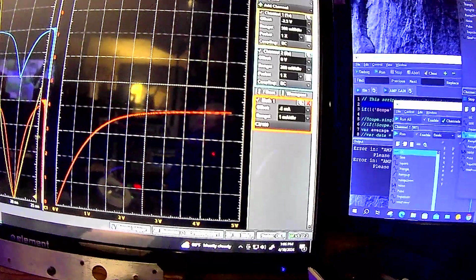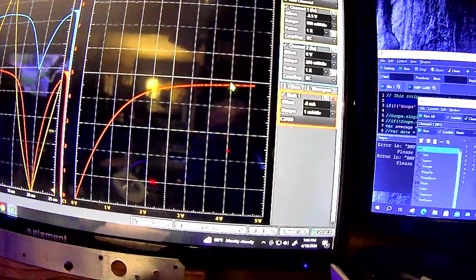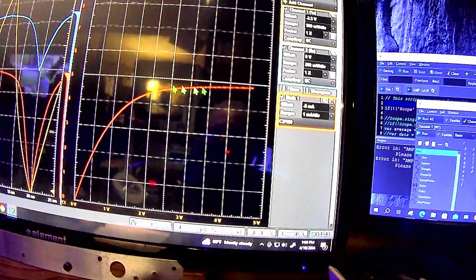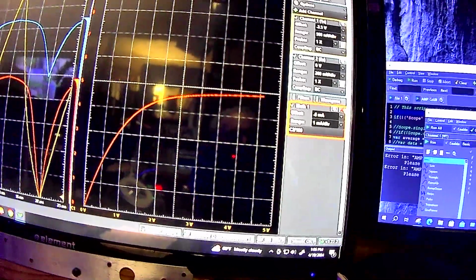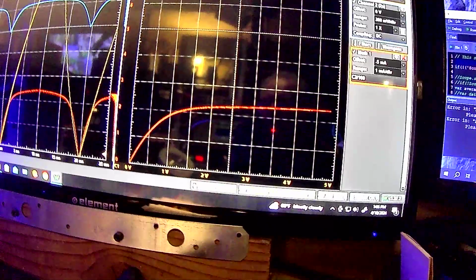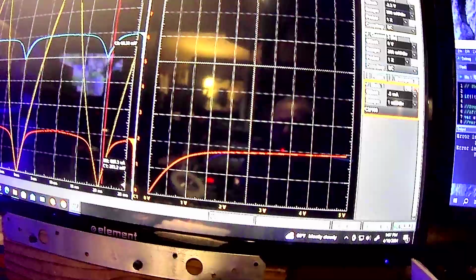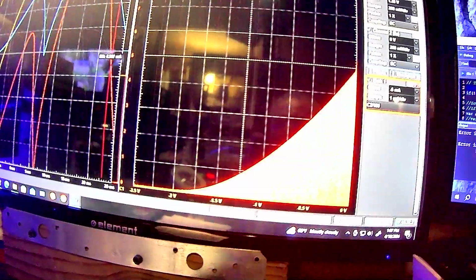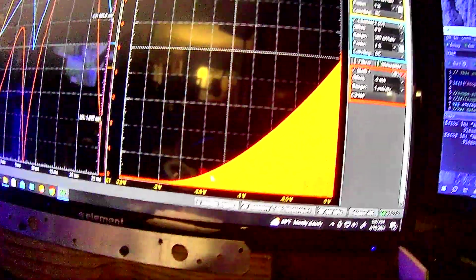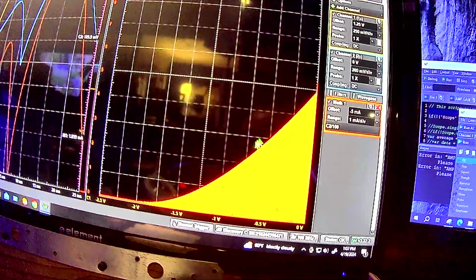It's about to kind of point out the ohmic regions, like at this maximum IDSS, are pretty much in here, right? But you can kind of see them with a family of curves shrink, where the ohmic region is much lower here. And if you go look at the characteristic curve, you can't see the ohmic region on this curve.